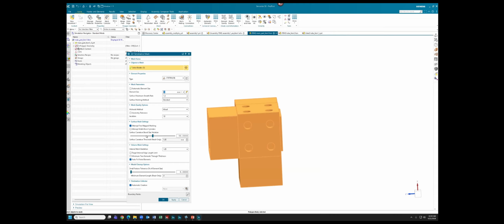And again, tons of different settings here for our TET mesh that you can leverage. Simcenter is really great about having all of those really fine-tuned geometry and mesh setting controls available for you. Some of the relevant ones: you can do things like minimum 2 elements through the thickness. That can be useful, particularly if you have a component where you want to capture some accurate bending stress.